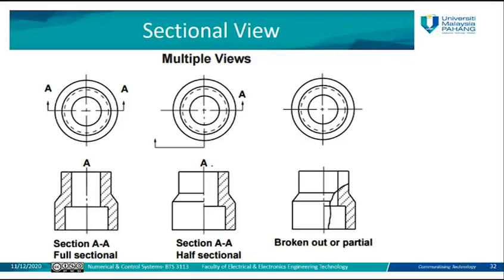So the first, for example, represents a half, so it will be the same as this half, but this one will be cut again in the other direction. It will be represented by this view, so you have more than one view. This is the view for the half, and this is the view for the quarter, for example. Because when you have two perpendicular planes, it cuts into 4 quarters. If you want to see the quarter views, it will be like here. The half views will be like this one.